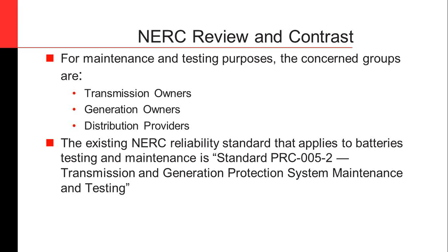So again, this is not an in-depth NERC review. Just wanted to highlight a couple of things. Obviously, NERC is for basically anybody touching the transmission grid, so transmission owners, generation owners, distribution providers. And the current standard that applies to battery testing and maintenance is PRC-005-2. You can just do a Google search for PRC-005-2 and it'll pop up. It's on the NERC website, and the title is Transmission and Generation Protection System Maintenance and Testing.